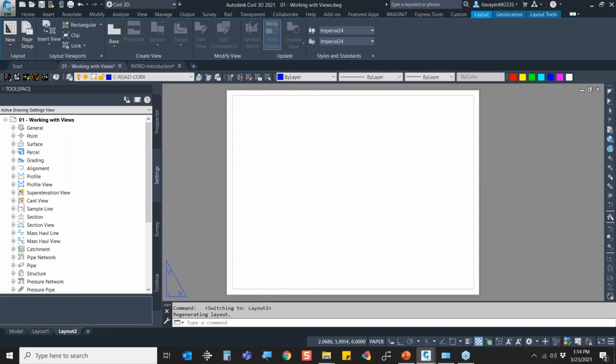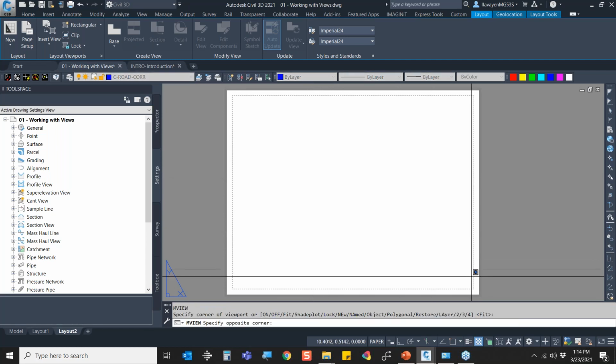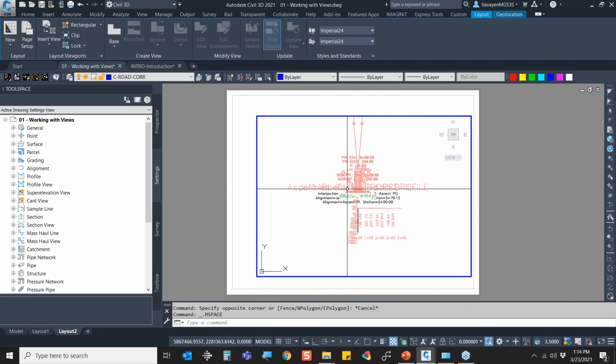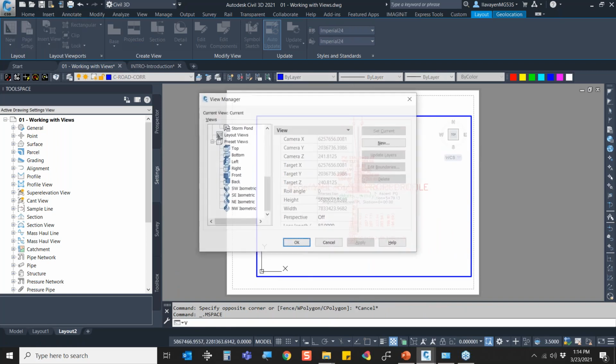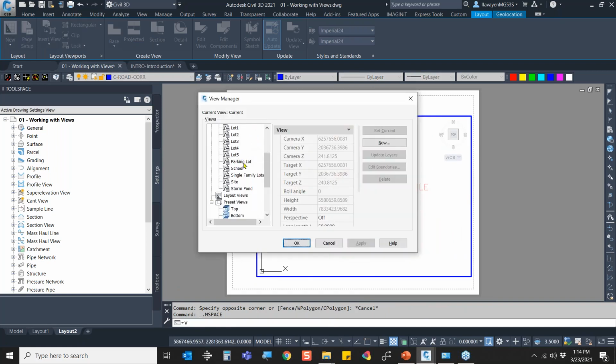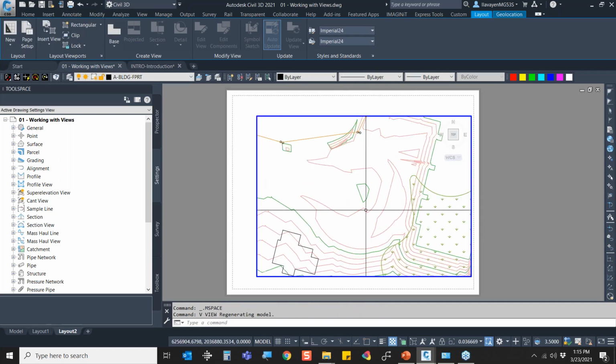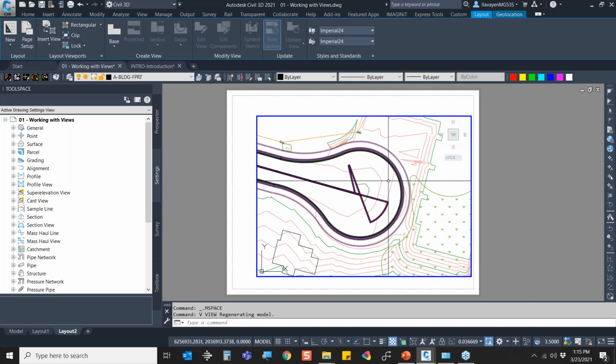Now, if you don't like that, yes, I can create my own viewport. Let me go here to make view for my viewport. I can zoom into here, and it gives me the whole Civil 3D drawing. I do have the option of loading the V for view command like I did before and zooming into a particular design. So it works in paper space and it works very well in model space. And I like how awesome it is to be able to just do a little bit of work and remember those zoom levels, especially when we're dealing with very, very large sites.